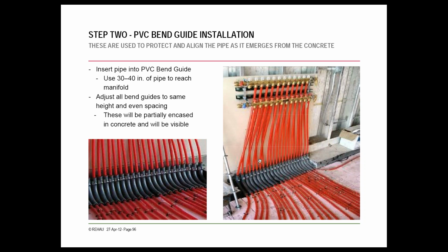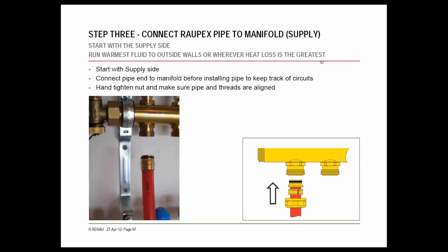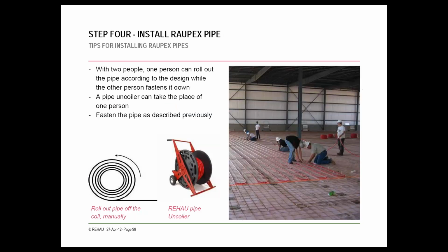Here's just two nice pictures of an install where they've used some unistrut and cushion clamps to line up all of the pipe ends nicely. As I mentioned, all the pipe gets secured to the manifolds with the bushing size for the pipe size.